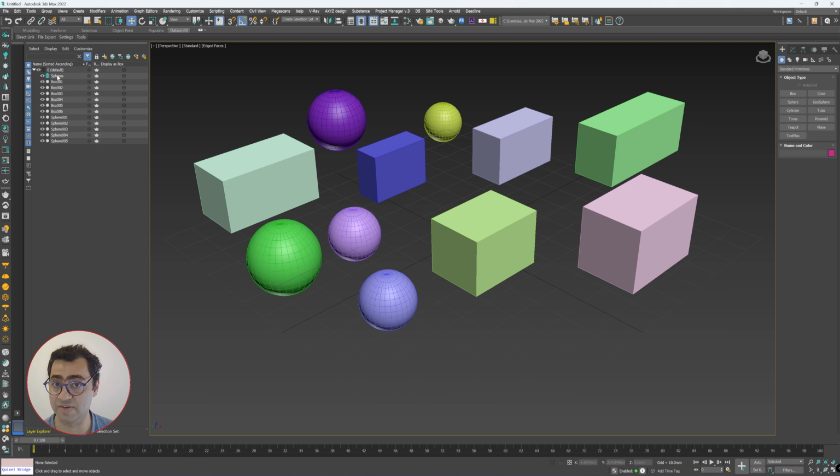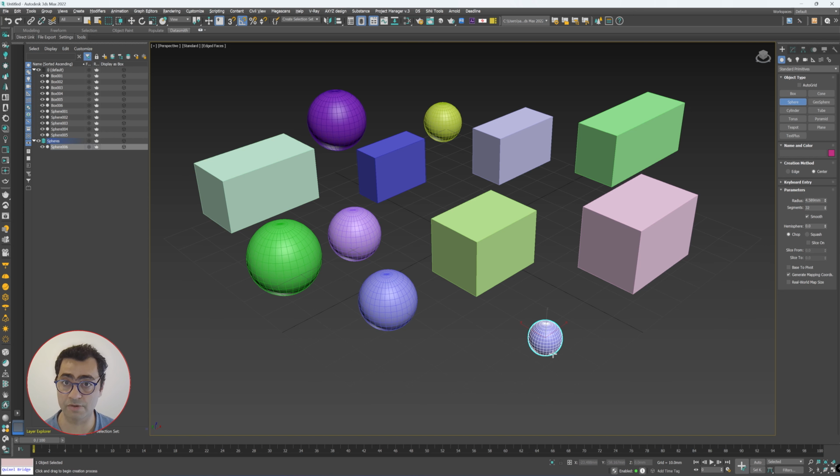So what you can do is here, you can actually click it and just drag it out, just put it outside like this. Also, the other bit is, just going back to it, this is the default layer now. So we can see the 3 planes highlighted. So at any moment you can change the default layer to whichever layer you want. By doing that, what's going to happen is that, for example, if this is the default layer, any new object that we create is going to automatically shift into this particular layer, which is super helpful.